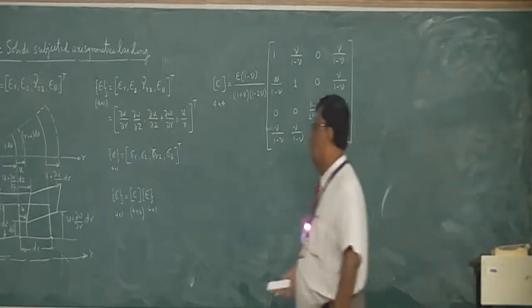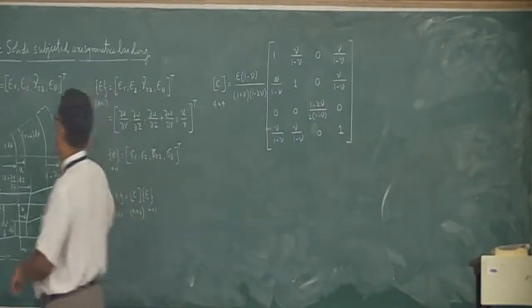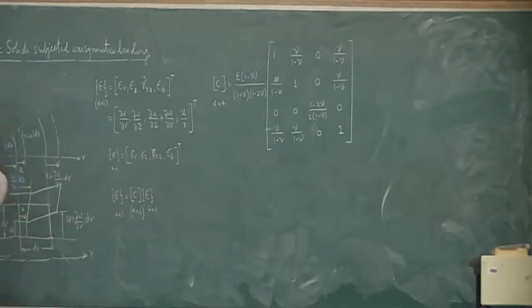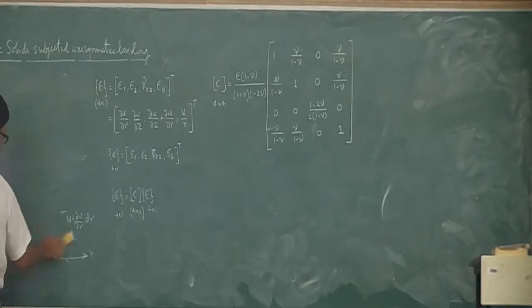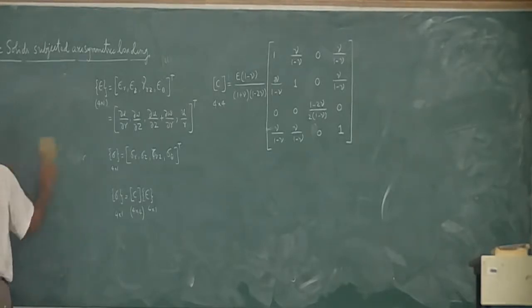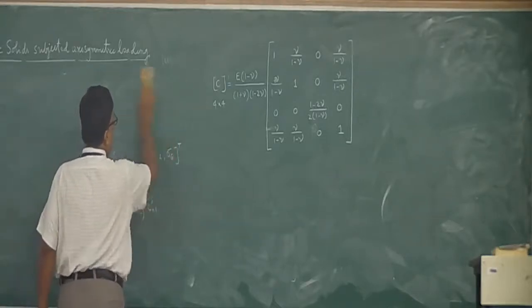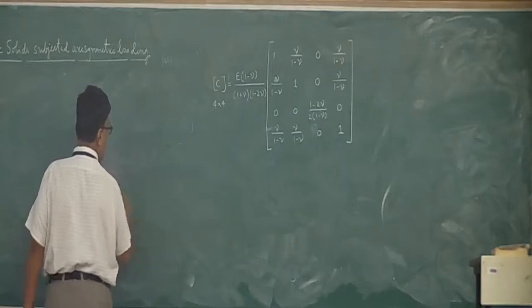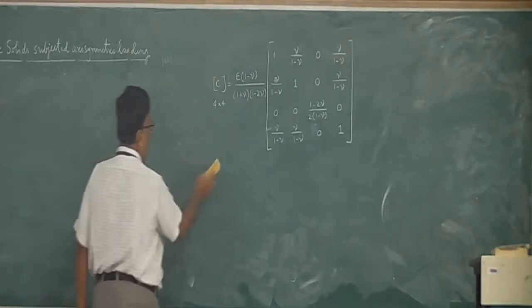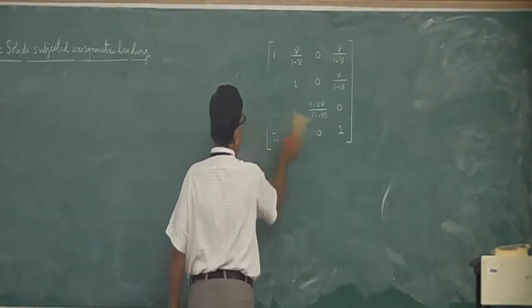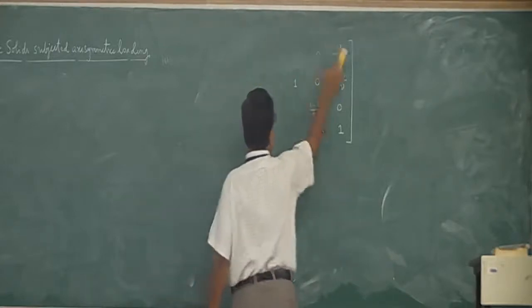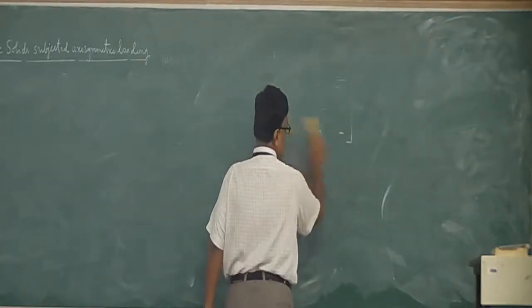Now let us see how we can make the finite element modeling, how to make the discretization and how to generate the given equation. Again, as I told you, it will be considered as a 2D element only. For example, if you are using a constant strain triangular element, it will be treated like a 2D element only, but there is a rotation in the theta direction, so that will take care of the 3-dimensional solids of revolution.